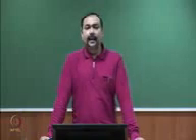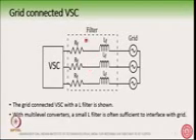Now whatever the voltage source converter may be, when it is connected to the grid, we usually connect it through a filter. As I have shown in this diagram, you have the voltage source converter, the 3-phase AC grid, and the filter. There can be different types of filters, like L filter, LC filter, LCL filter, and even higher.